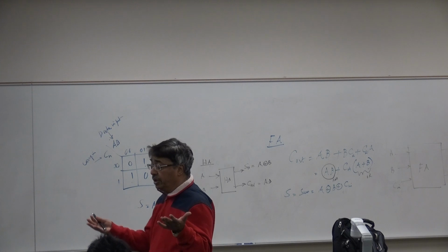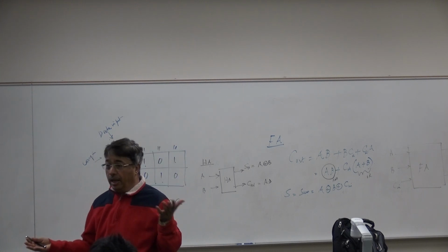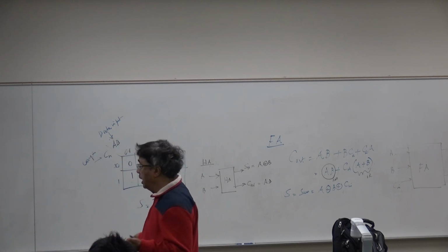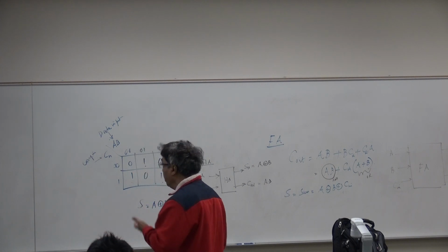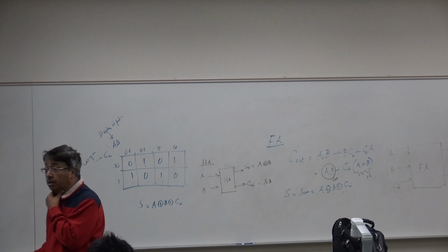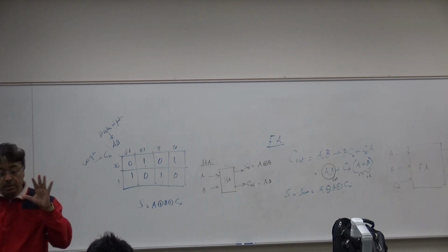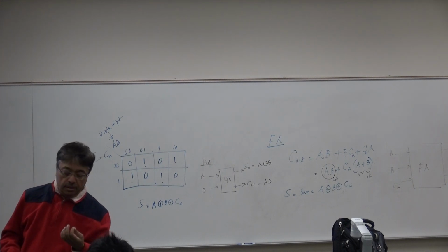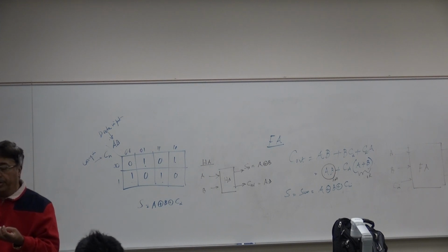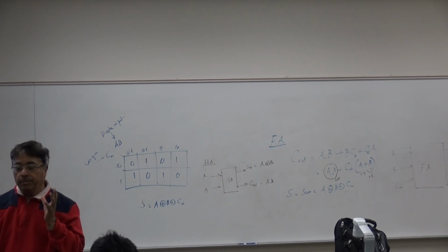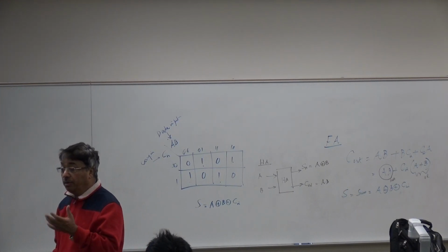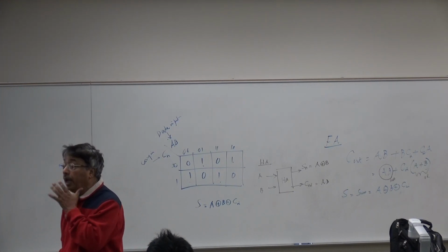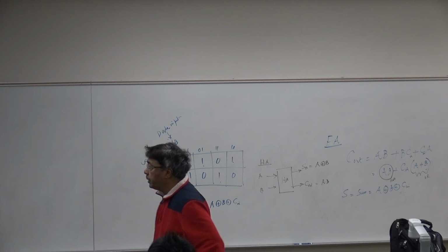So that's the difference between logic design and circuit design. Logic design, yeah, this is good, and you don't have to really bother. But you are a chip designer. If you just transcribe that logic function, then you'll find out that your performance will not be very good. So there are some things you need to do to improve the performance in terms of speed, and those are the things we'll talk about.